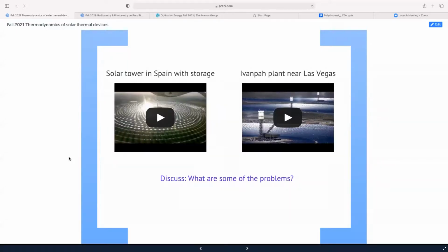Of the absorber, you mean? You're talking about the absorber, right? Yeah, that's a good point. Yes, now I see. I didn't think of that. What you're saying is that the incident angle of the light from the heliostat will be at a weird angle to the absorber. And as we saw in a previous lecture, with that angle you have the cosine theta loss. You want that to be as normal as possible. That's a good point. I didn't think of that.